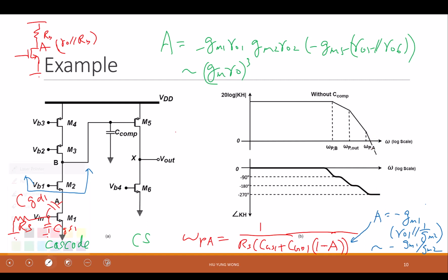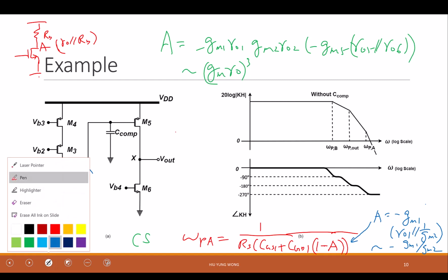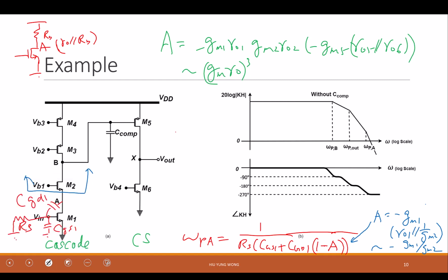So where is the gain crossover frequency? On the top, by definition. Thank you. This is the gain crossover, right? Where's the phase crossover frequency? Here, right? Omega px. So is this stable? Now this is stable by itself, but once I put in feedback, it is not. Is it stable in feedback? No, right?